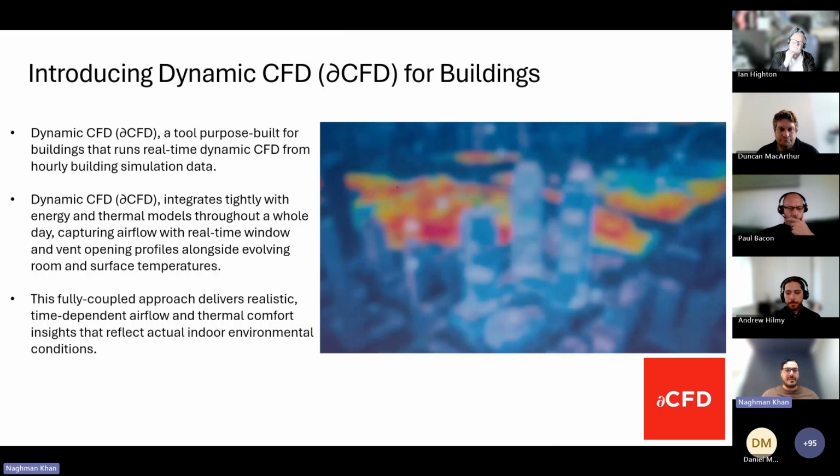And maybe, Ian, we could spend a minute just on that. Yeah, by all means. Basically, if you look at most CFD packages, the commercial ones like Fluent, etc., they use a thing called pressure correction. So mass conservation is a tricky thing with the Navier-Stokes equations. That's as far as I'm going to go. But what we've come up with is a neat way of eliminating pressure, which means we've got a lot more stability. We're not using pressure correction. And another fundamental feature of it was the fact that it's 100% stable.